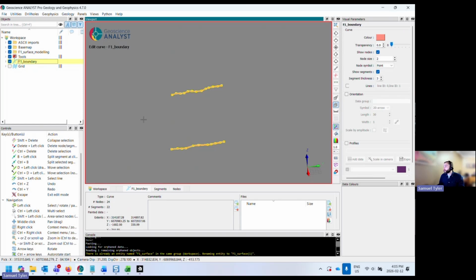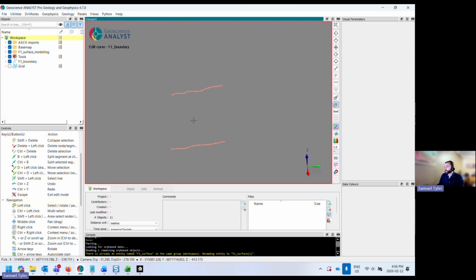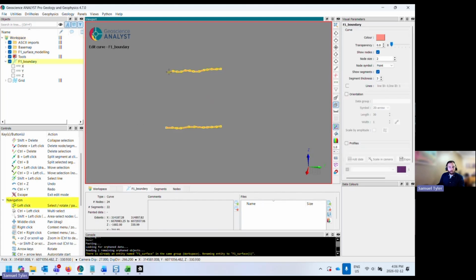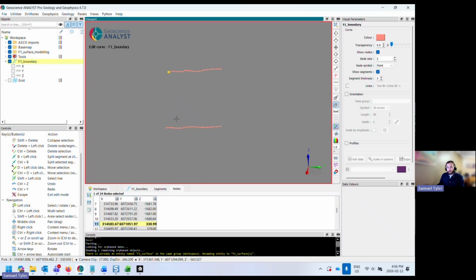There's a couple line construction tools I haven't talked about. That's joining and closing. So we've got different icons here to indicate whether this is an open curve, it's not connected in a loop, or it's closed. I'm going to close this by making sure this is at the node level, pressing J, clicking on one node and then the next one.